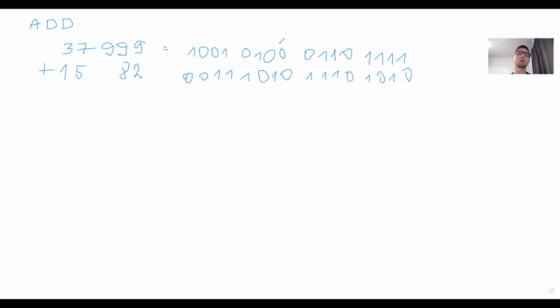So can we use an 8-bit adder to add two 16-bit numbers? We have the bottom 8 bits and the top 8 bits for each number. So let's see, how would we add decimal numbers? 9 plus 2 is 11. 9 plus 9 is 18. This is 7 and 5, 12, plus 1, 13. And here we would have 3 and 1 is 4, 5. So we should get 53,081. Okay.